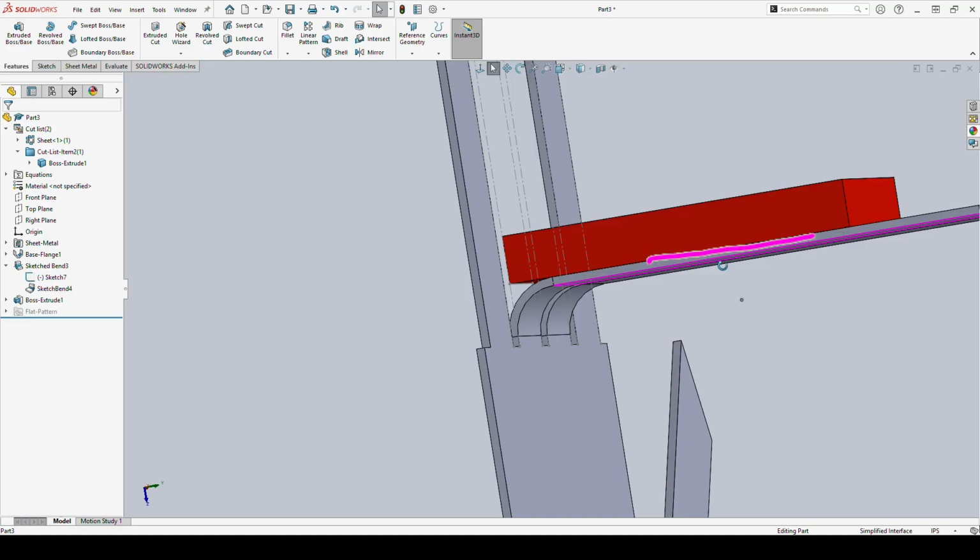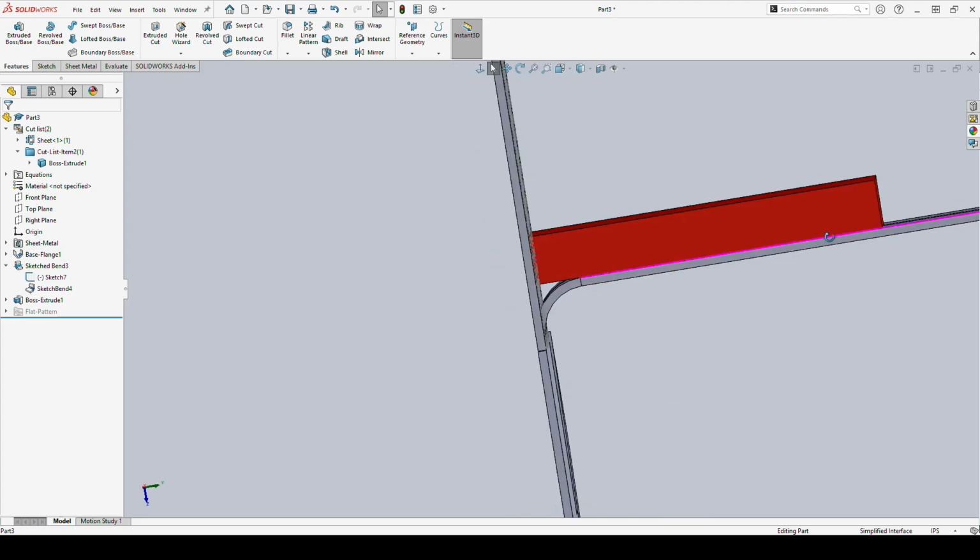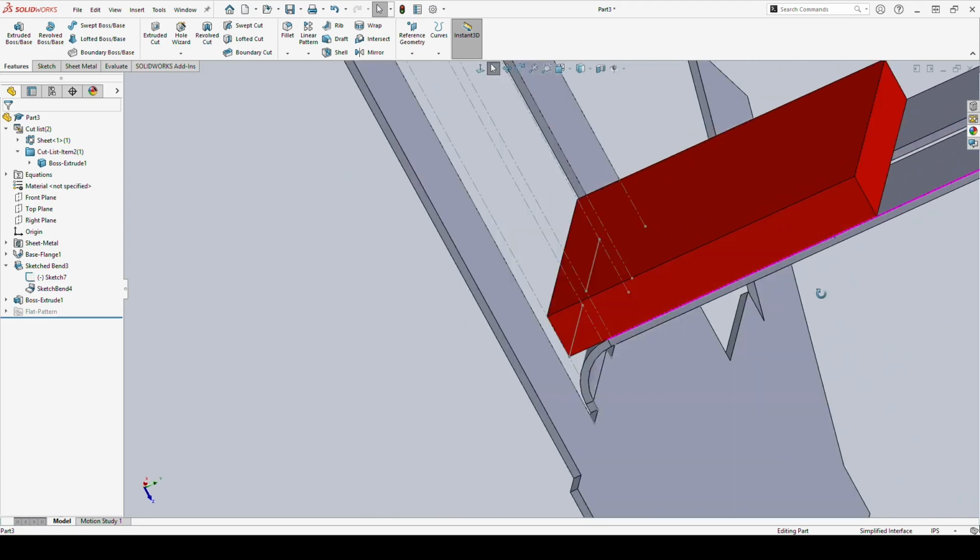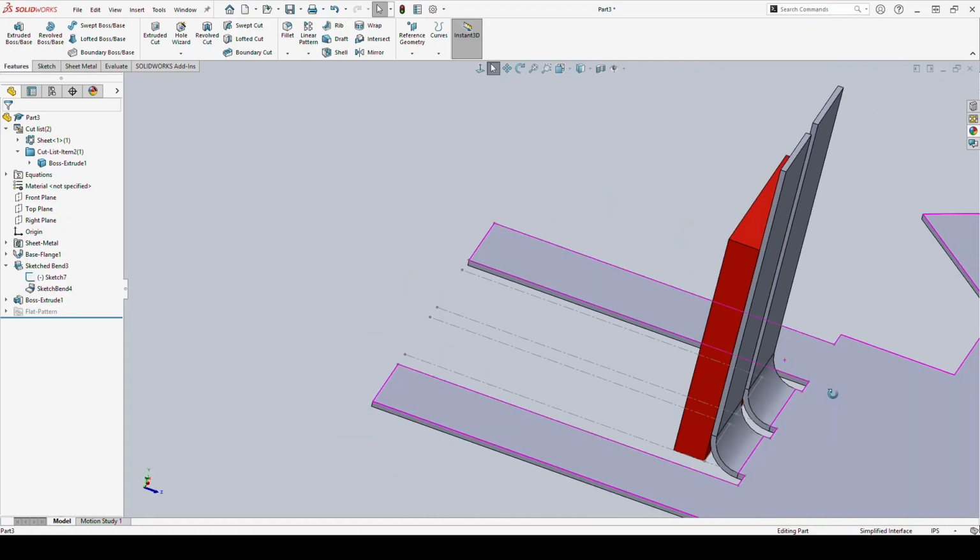This is important if you are creating a sheet metal piece that has to fit in something. So our critical dimension is how big is the outside of my box, how big is the outside of my curve. And that is a way to set it up so that that is your critical piece. That is where all of your dimensions are set up. Everything's working out nicely for you at that point. You're not making any mistakes.